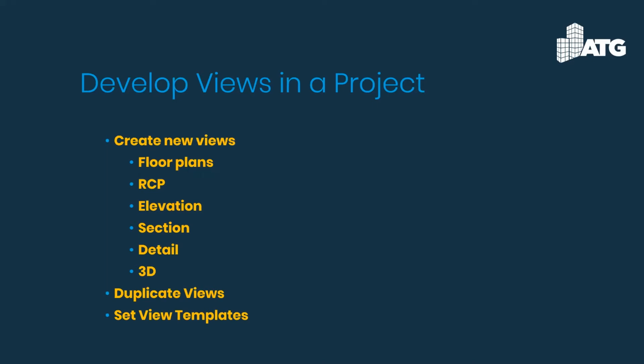So I don't technically delete the views, I delete levels, and it does that for me, and obviously shortens up that list within the project browser. So again, I see that as being more of a benefit to pre-creating those. Now, also building them up as you go. Again, if you have the CTC Express tools and have the view creator, you do have the option to utilize that to quickly and easily develop new views within a project as well.